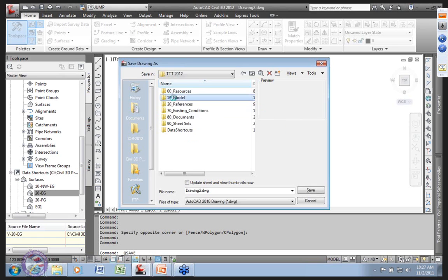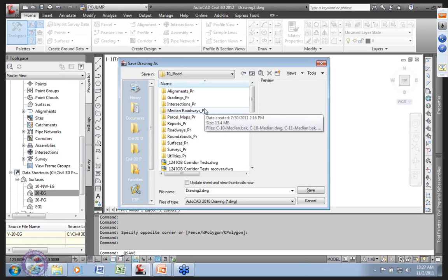We also, if we're building a model, divide things up in a project-based approach, but if you look at this carefully, this list of folders under model are feature-based inside Civil 3D instead of output-based. And that is an important concept since we need to keep the features and manage that interaction together.